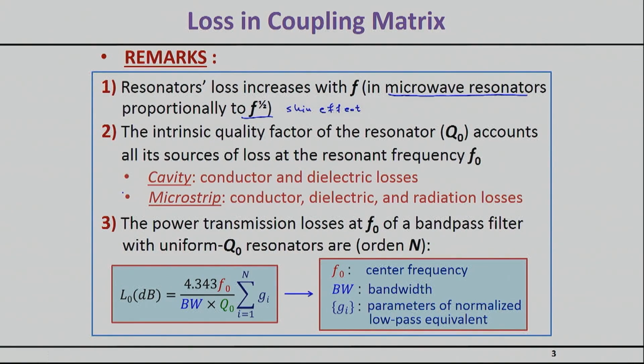Also, the second thing you should keep in mind is you should be careful of the technology you're using to properly reduce loss where necessary. For example, in cavities, a technology that utilizes closed resonators, your radiation is practically zero, and you need to pay particular attention to dielectric loss, because usually conductor losses are low.